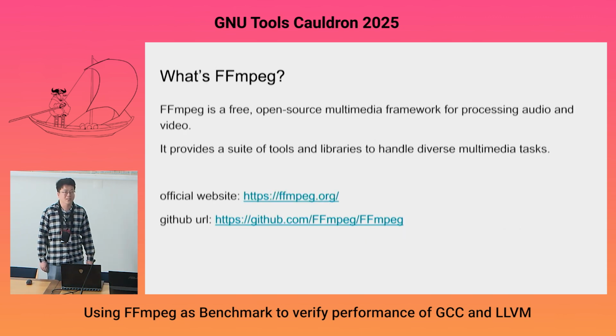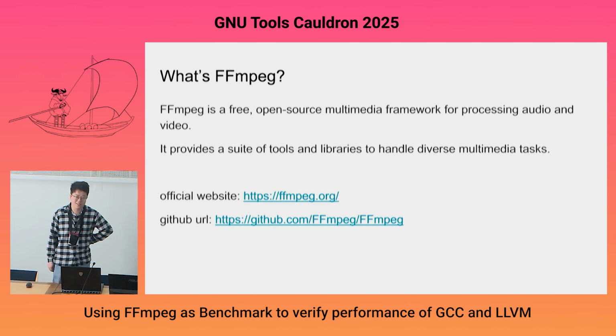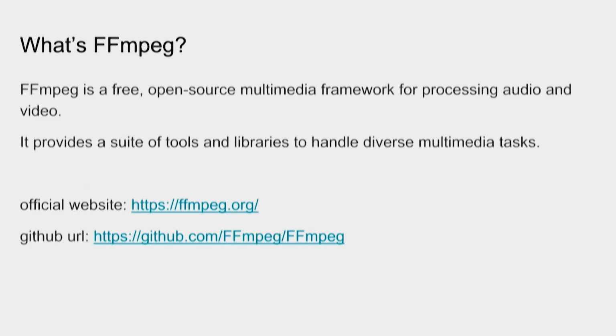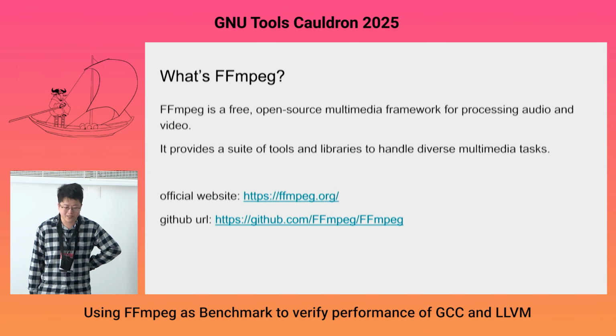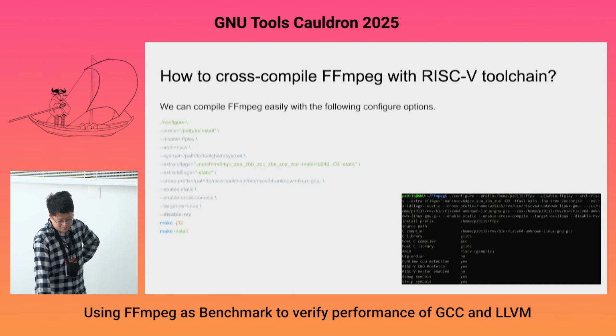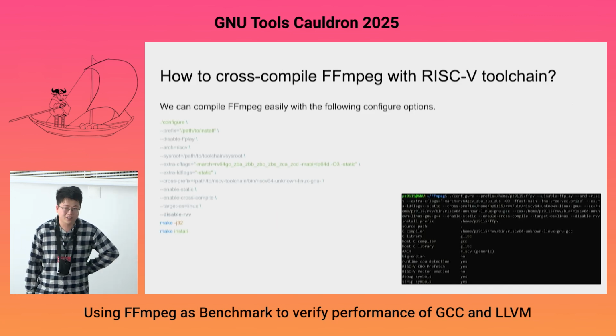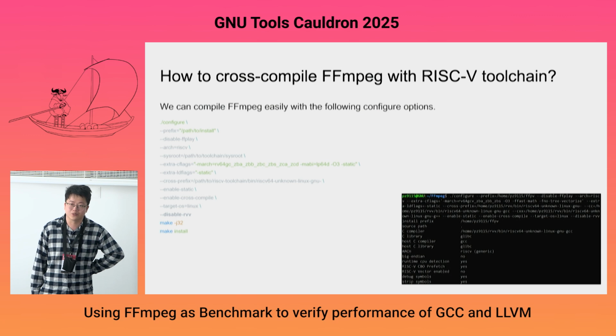Firstly, what's FFmpeg? It's a widely used workflow that you can use to encode or decode videos. It's free and open source, and we use it on a RISC-V board, and to run it on a RISC-V board, you should cross-compile it first.